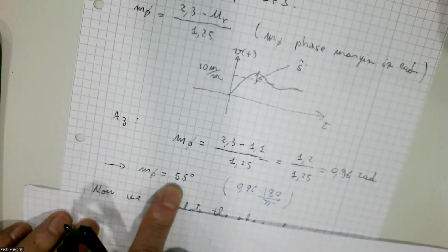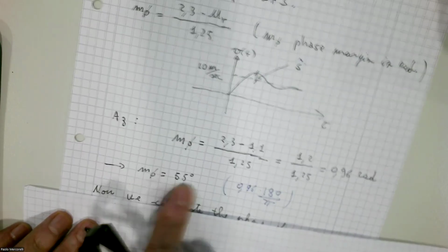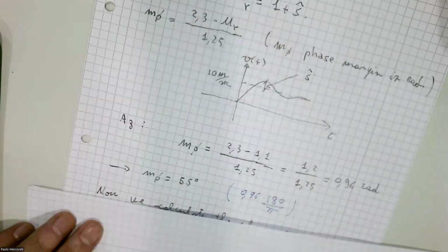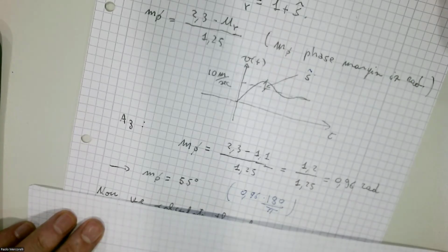I need the phase margin 55. This means minus 180 plus 55. This is a little bit more than minus 120, minus 125. This is what I need, because I need an overshoot of not more than 10%, in accordance with this approximated equation, which I will clarify a little bit next time, where it comes from.